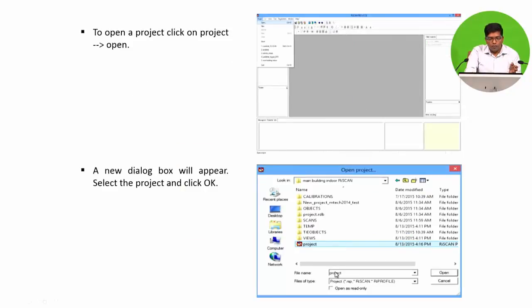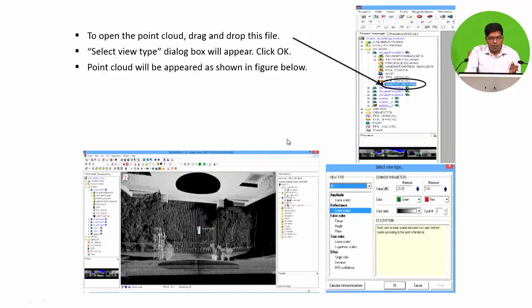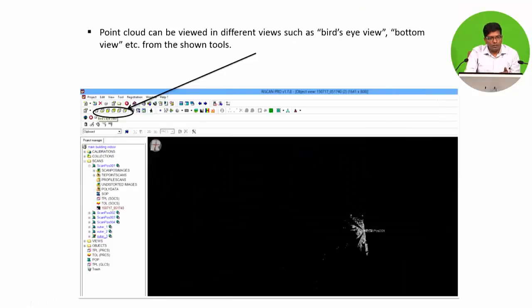Okay, so then accordingly the naming has to be done, and then we have to give the various descriptions of how much increment we are going to make in terms of horizontal and also vertical. And once those things are done, the operation of the TLS starts, and the data is acquired both in horizontal and vertical. You can see that this is the position of the laser scanner, and the entire scene of 360 degrees is acquired, and in terms of vertical, since the angle was given up to 100 degrees, only a certain area just above the TLS was not acquired, and this TLS data can be visualized.